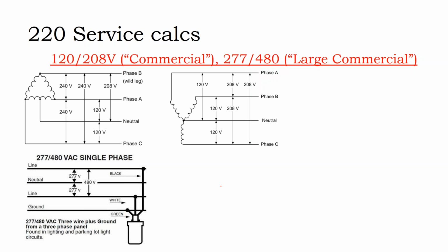undersized neutral. If you have a fault from one feeder circuit and that's completely off, you can imagine a number of circumstances where one circuit is off and the other's on. So normally with solar, you're not going to have an undersized neutral. You want to just keep the neutral the same size as a starting point, unless you can find a reference in code to undersize it.